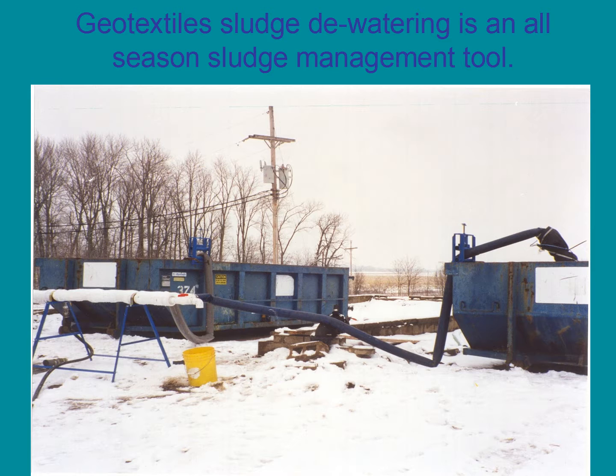Geotextile dewatering is an all-weather system. Sludge freezing in the bag will not shut down the system. Sludge freezing in the piping system or the drainage system will, however, so care and thought should be used when designing the system for cold weather zones.